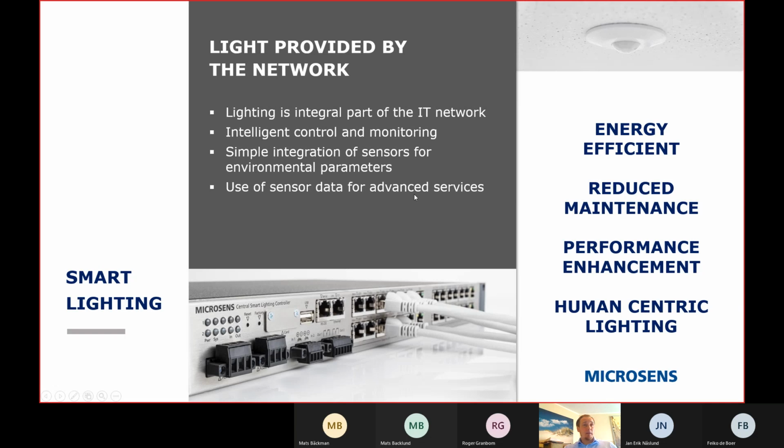We have human-centric lighting and automatic light adjustment, which we call auto dim. We measure the brightness inside a room and compare it to the set point to reduce the lighting. When there's enough outside light coming into the room, we reduce the electrical or artificial lighting to save energy. We have also created a follow-me light function, which means for runways or hallways, the light doesn't have to be on for the full course. The light follows you along the corridor. So when you enter the corridor and maybe stop halfway, only half of the light has to be on, instead of the full corridor.